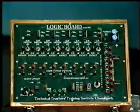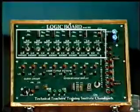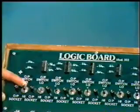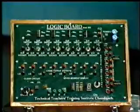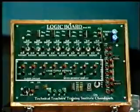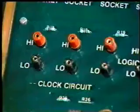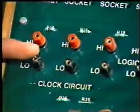The variable logic output section provides 8 high or low logic inputs to the circuit under test. With the help of toggle switches, the output can be selected to either high or low. The fixed logic output section provides inputs to the test circuit. This input is fixed and cannot be varied. Red sockets provide high output and the black ones low output.